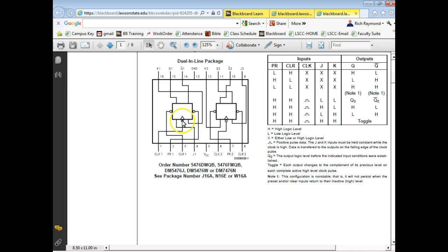But when I get over to this guy, this is what we call edge trigger. So anytime when you're looking at a schematic and you see a pin that's got this little triangle on it, that means it's edge trigger or edge enabled. The term we use is trigger. And the bubble means it's triggered on the falling edge. If I'm going to make something synchronous, I can't synchronize with a level. Y'all understand why?